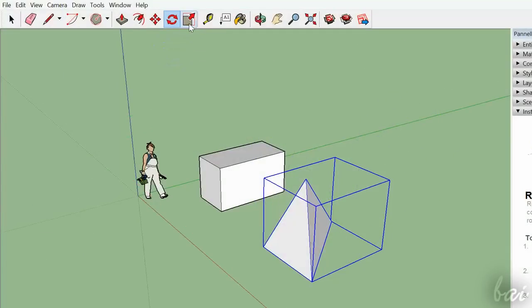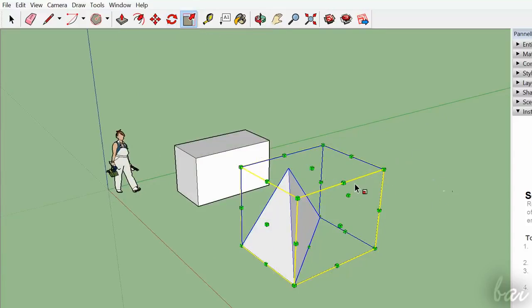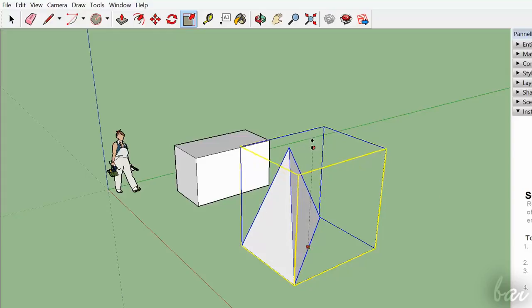The Scale tool is used to scale and deform the objects selected. When you enable it, a yellow structure appears. Hover on each green cube to know what's the exact direction you are going to deform or scale the object. Then just drag the cubes.